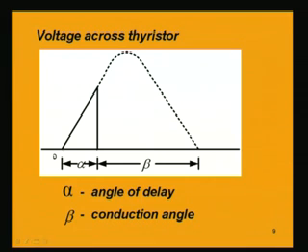So, during this portion you see the voltage is equal to the input voltage. After that point of firing, the thyristor voltage becomes 0. So, this is the principle which will be applied for power control. So, what we are discussing is the AC phase control.